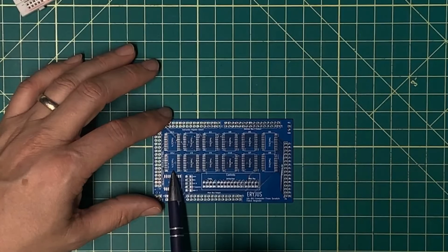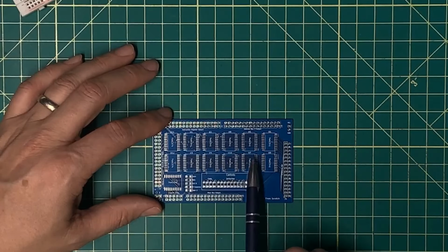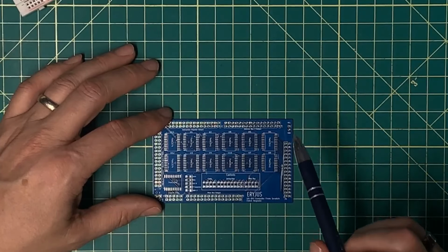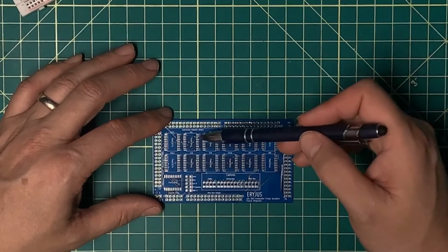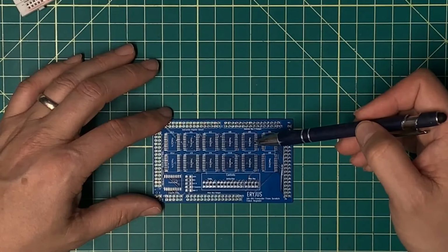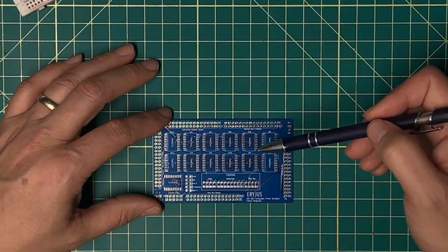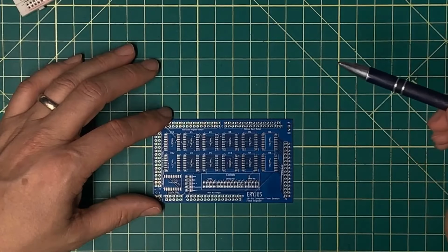I have a register here, a D-type latch, 74HC574, and that actually stores the contents and then hands that out onto an internal bus to a number of line drivers. Now, the line drivers themselves, one goes to displaying the contents of the fetch register. Four of them are asserting out onto different buses: ALUB, the main bus, address bus 2, and then the bus that goes from the fetch register to the instruction register.